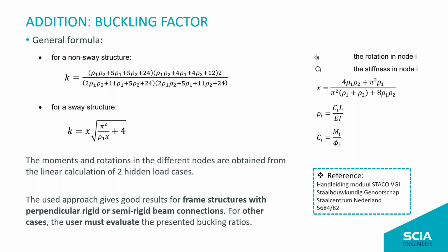Do a second order calculation, put in your imperfections, and allow ignoring buckling. And they will always be properly considering the second order effects of your structure. But of course, we don't all have time to do all the nonlinear calculations of an immense amount of nonlinear combinations and the imperfections, or to do a stability calculation for every element in your project.